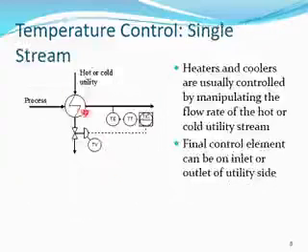Temperature control signal, for example, this heat exchanger. Same. This is a hot or cold utility. This is the process flow that needs to be controlled. The temperature here needs to be controlled. It's the same. Temperature valve, same like that. Here it depends if we want to heat or want to cool down.